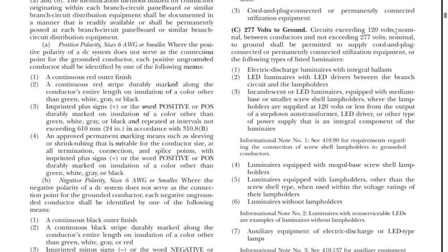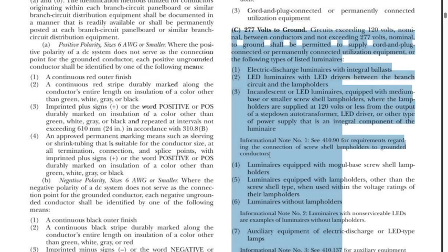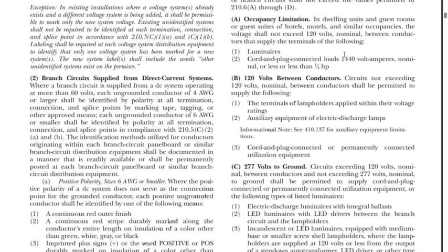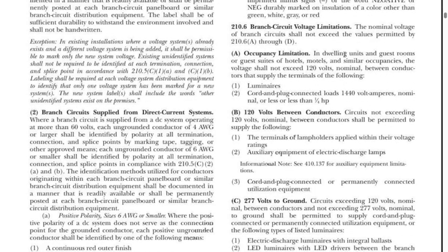In other words, and it says it right here, when you leave 120 on your lighting circuits, the maximum you can go then on lights is 277. It's really what all of this is saying. In a lighting system, it's either 120 or your lights are going to be 277. We really don't have any voltages in between those. All right, so that's what B and C are talking about. But let's look at A for a second. I jumped A. We'll go back to A for a second.